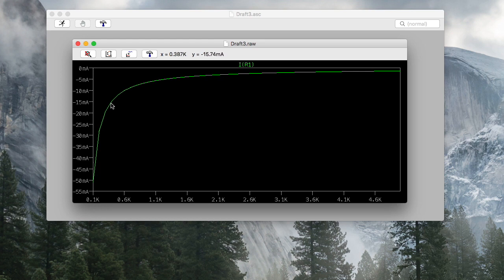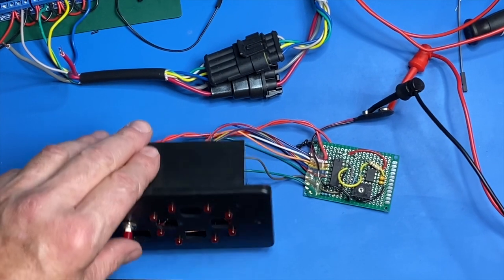So you'll see 380 ohms. Anywhere from, I would say, 200 ohms to 400 ohms would produce a forward current through the diode of anywhere from, I would say, 8 to 15 milliamps, which is optimum. I will probably opt for the lower end of that.